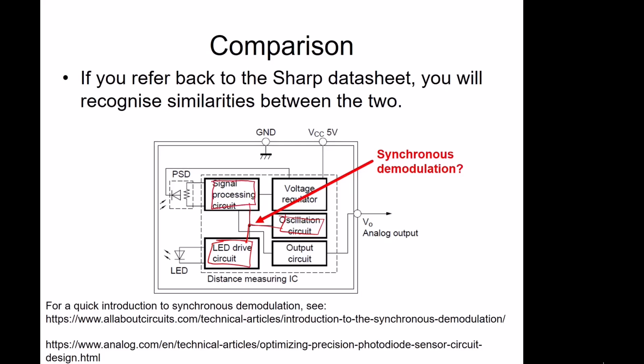So the frequency it's being driven at is also being used to analyze the signal. We did this by using a bandpass filter. That works. The slight problem with that is that you've got to design the filter specific for the driving frequency. So it does work, but you've got to design it appropriately.